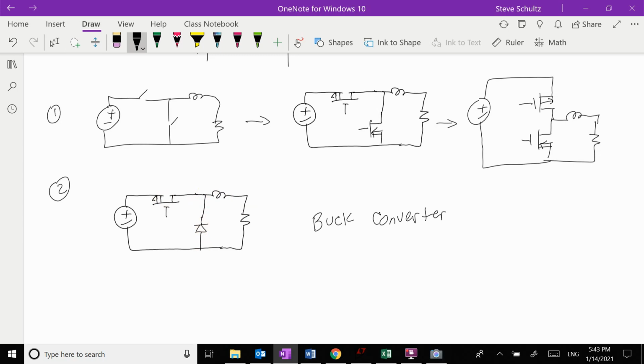It's basically just a PWM, a pulse width modulated signal, that has an inductor as a filter. And then if you want to get fancier, I can do another pole filter, and you can even add on a capacitor there to smooth it even more. So then I get a two-pole filter. So this is the basic buck converter that we're going to be analyzing.